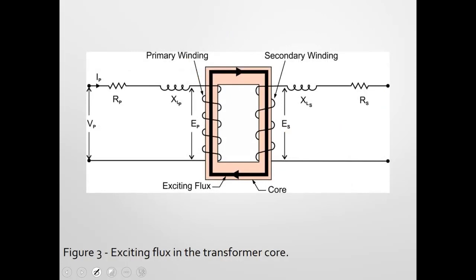Now, what's happening during no load conditions? This is the preamble for when we go to load conditions, understanding what's going on. If I put my applied voltage on here, 240 volts, we would see a little bit of current flowing through this primary. And it is just a chunk of wire. Why isn't it a really, really high current? Well, it's a coil, and it has an iron core, and it's going to create counter EMF in that coil, which opposes our primary voltage. And so we end up getting just a little bit of current flow through that.